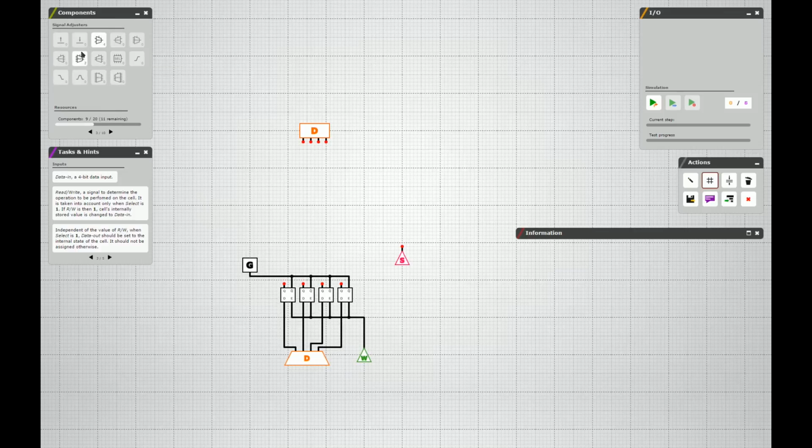And the only thing, what about a multiplexer? I think this is a 4-to-2 multiplexer, the simplest multiplexer, taking a pair of signals controlled by just a single select wire. This multiplexer selects either the first pair of inputs, select equals 0, or the second pair, select equals 1, and moves it on to the outputs. 4-to-2. We would need 2 of them.